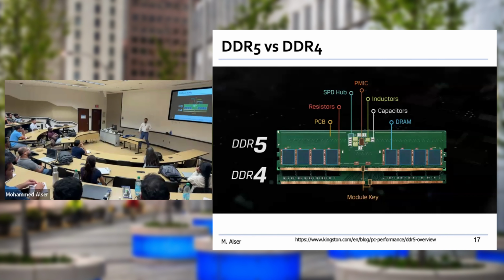Excellent. So I think why they changed the interface into DDR5, I don't know what was wrong with DDR4, why they have longer side than the other one. Okay, that's one thing. But why they make it in DDR5? So they split the channel, which is the 64, into 2 sub-channels. Okay, so in terms of the design or architecture level, they try to improve that internally.